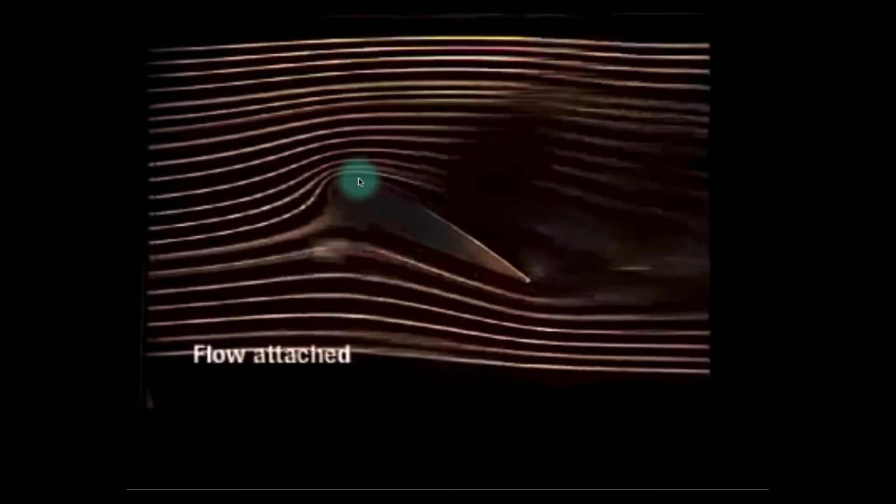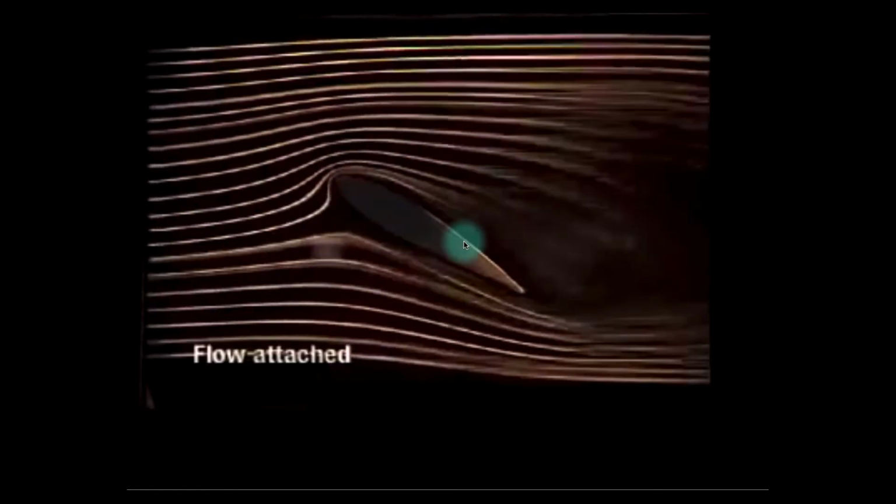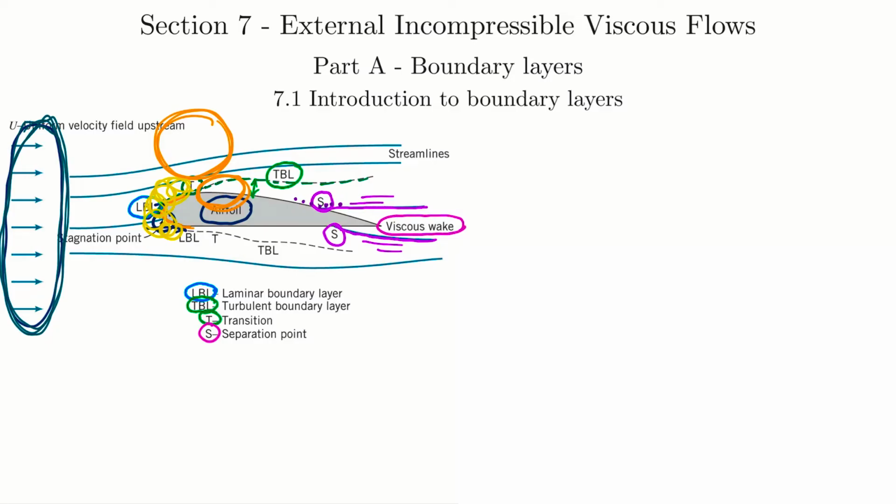So as you increase the angle of attack, the lift's going up and up. You're getting higher and higher velocities on top here, slower and slower velocities here. You're getting separation here, here, here, and then it's sort of like all of a sudden the separation point moved up so that it was at the top of the wing and you had no flow against the top surface anymore.